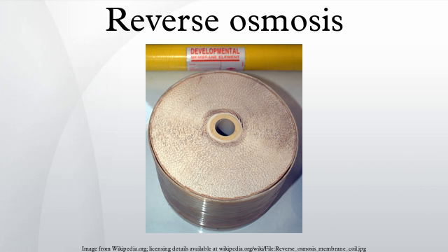The cellulose triacetate membrane is prone to rotting unless protected by chlorinated water, while the thin film composite membrane is prone to breaking down under the influence of chlorine. In cellulose triacetate membrane systems, a carbon post-filter is needed to remove chlorine from the final product, water. Portable reverse osmosis water processors are sold for personal water purification in various locations.